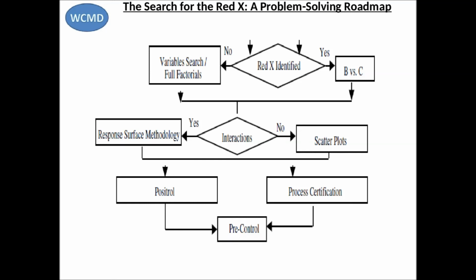But that is still not the end of the road. Problem solving and product process characterization must be followed by product process optimization. This means establishing the optimum target value, specification limits, and tolerances for the previously characterized input variables. Scatter plots are adopted to achieve realistic specifications and tolerances when there is no interaction effect, while response surface methodology offers a methodology to optimize interactions.